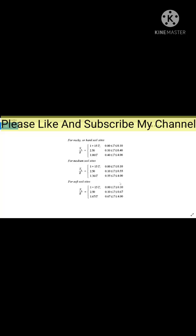So you can see this is your Sa by g factor, or Sa by g as per IS has been given in this way, that it depends upon two factors. One is soil type, which kind of soil is used for the construction, or which type of soil is there under the construction. Okay, whether it is hard soil, medium soil or soft soil, based upon which Sa by g will be calculated. And the second factor which we need to consider is the time period for which the earthquake load is going to act upon that building. So that time period also matters.